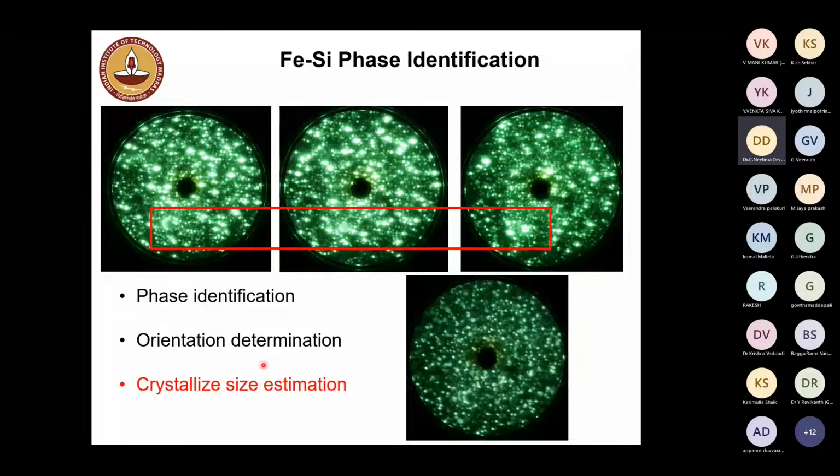If you combine atom probe tomography with field ion microscopy, then you can get the phase identification, orientation determination, as well as precise crystallite size measurement at the nanometer scale. That is all possible. So I hope this gives you a broader idea of how atom probe is absolutely crucial compared to other characterization methods if you want to see nanocrystalline features clearly identified.